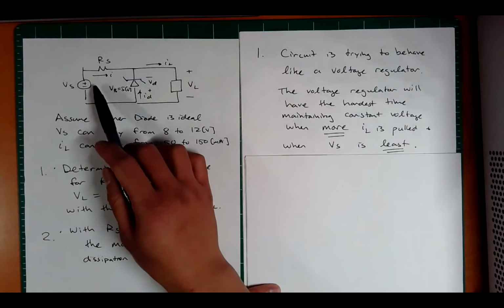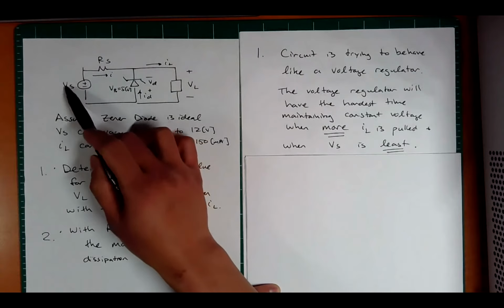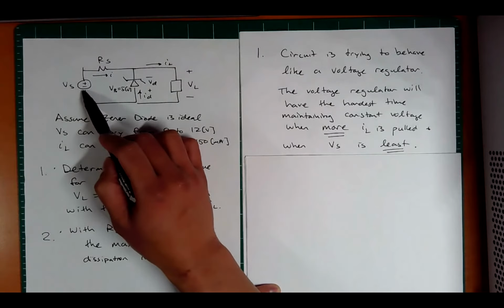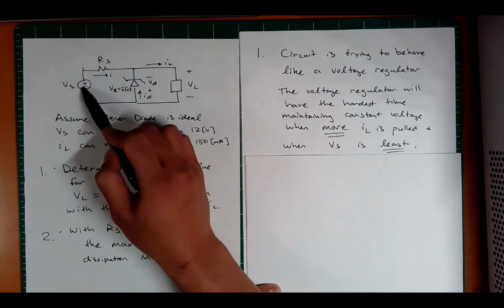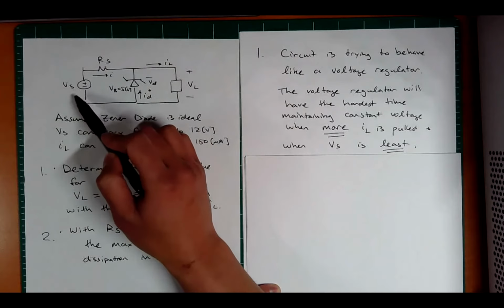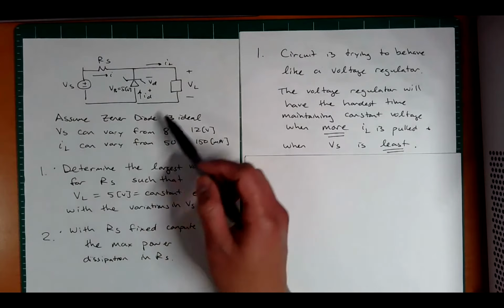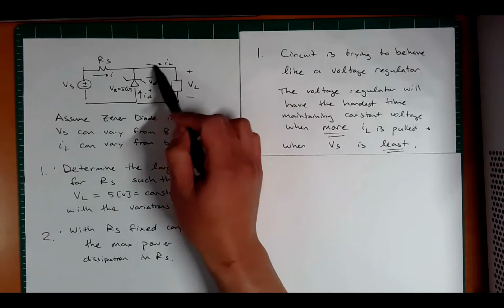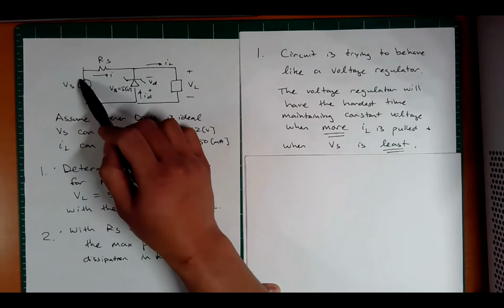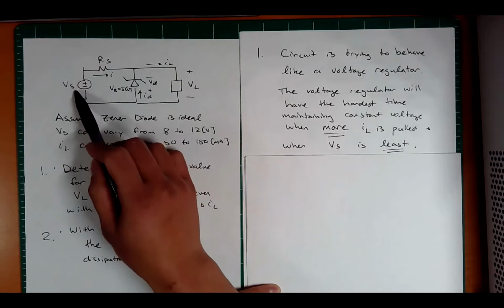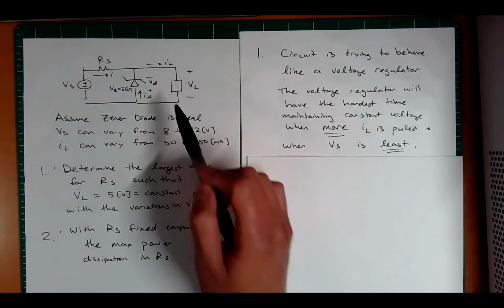The other thing you can think of is, remember the hydro analogy, voltage is pressure. What if this voltage pump back here is actually putting out the least amount of PSI? Well, if you're pulling more current, this thing wants to droop, right? And if you only have 8 volts or 8 PSI as opposed to 12, it's also going to have a hard time maintaining this voltage.